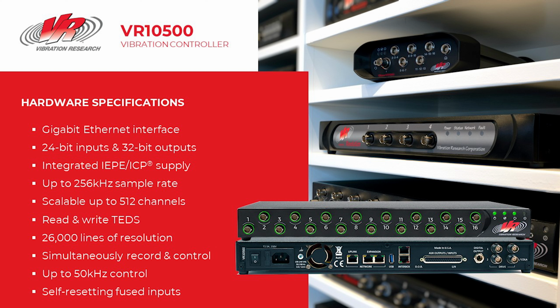It's scalable, also up to 512 channels. Like the 9500, the 10500 has an integrated IEPE power supply to provide power to those IEPE or ICP type accelerometers or transducers. It also understands TEDS, that transducer electronic data sheet, so we can read and rewrite the data on the TEDS chips. It supports up to 26,000 lines of resolution, also has 200 volt tolerant self-resetting fuses on the inputs, and it does not require any special board in the controlling PC.